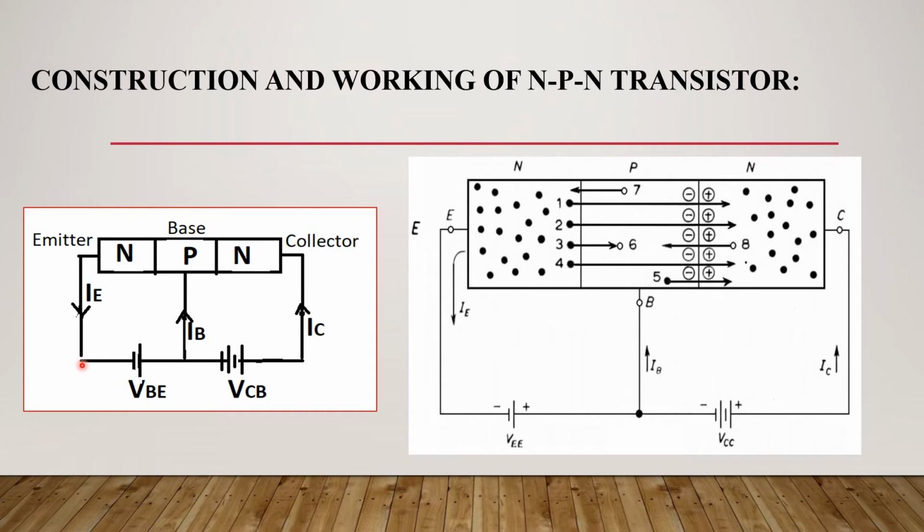In this, actually, IC flows freely through this device between the collector and the emitter when the transistor is switched fully on. However, this only happens when a small biasing current IB is flowing into the base. Okay. At the same time, allowing the base to act as a sort of current control input.